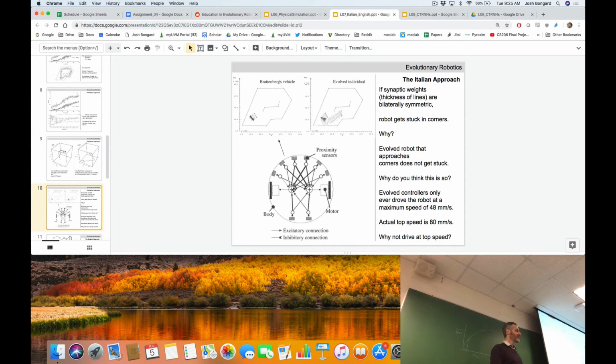The left motor stops. The left motor is going to more likely turn back, because remember, negative means rotating backwards. It depends on what, obviously, the other incoming synapses are trying to get the motor neuron to do. But if we just focus on that one sensor-motor pair, more stimulation on one side causes more inhibition on the contralateral or other side, which means the wheel either slows down or starts to turn in the other direction. And assuming the right-hand wheel is turning forward, it will turn away from the obstacle.